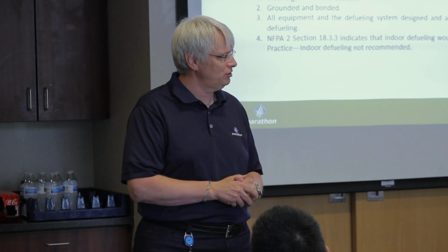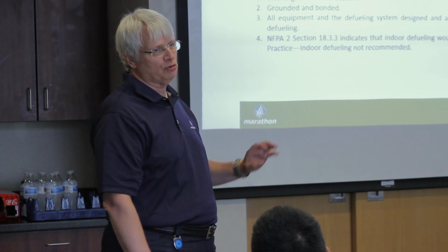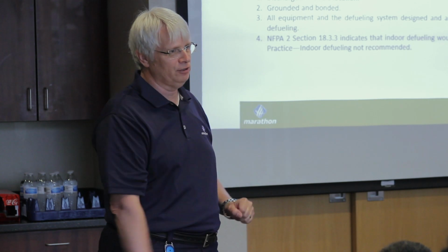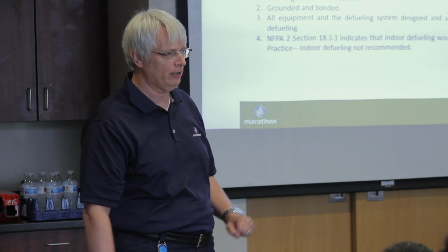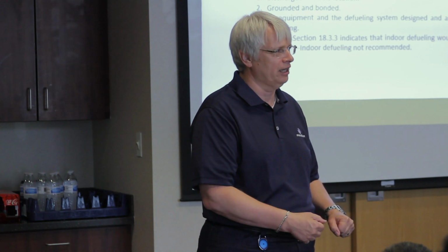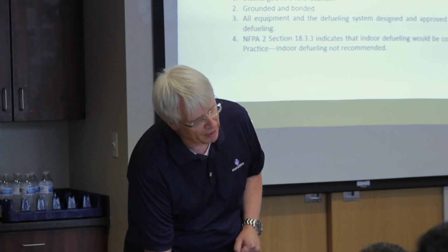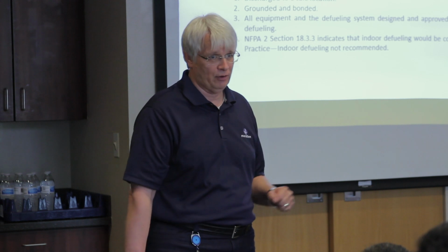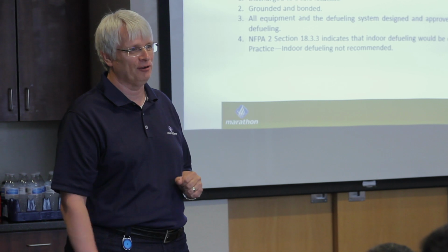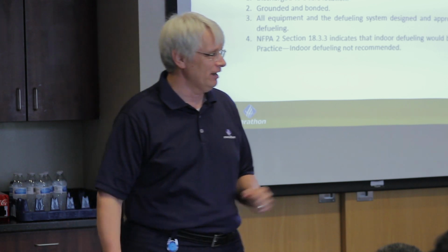So I was getting sort of impatient, and I had this tank kind of off to the side. And this was before these codes existed. We didn't ground anything, we didn't have vent stacks. We just sat it down on the ground and opened the valve, held on. So I'm doing that, it's taking a long time. So I opened up the valve a bit more, and I just kind of adjusted my body weight, and I put my knee down on the ground, and I became the ground. And you'd be surprised how much electricity flowing gas can generate. That static charge went up my arm and down my leg, and I was gimpy for the rest of the day.